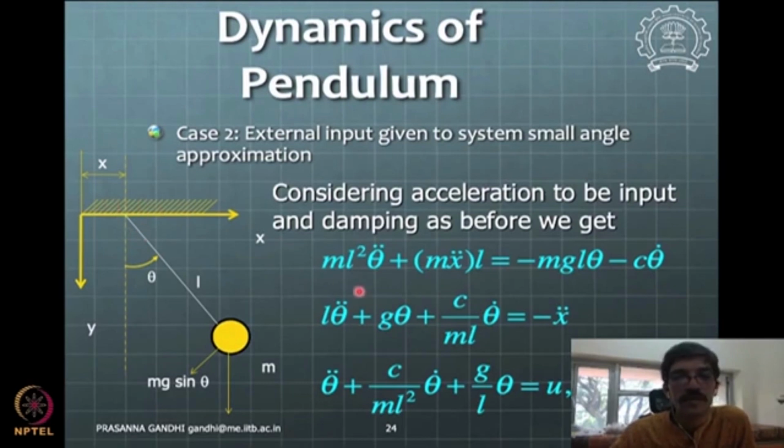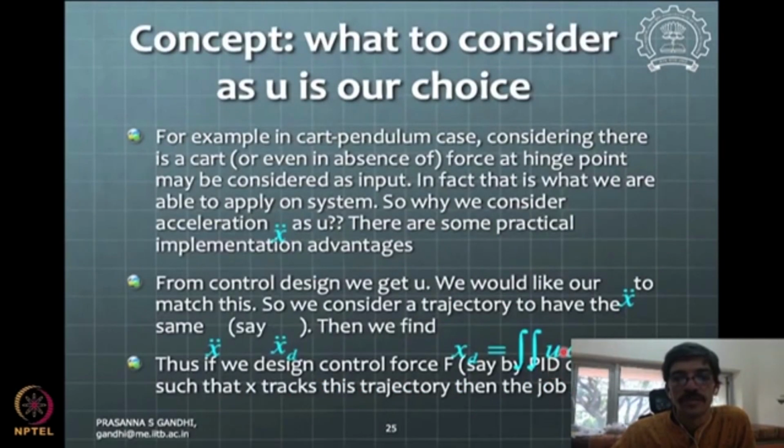And with the approach that we are discussing here right now, all those complications of under actuation will be gone here if I consider U to be this kind of input, and I implement this U by using this double integration and say some kind of a PID controller. Now there are some mathematical questions that one may pose, that okay, how do you guarantee that we will be able to track this xt trajectory very well by using some PID controller?